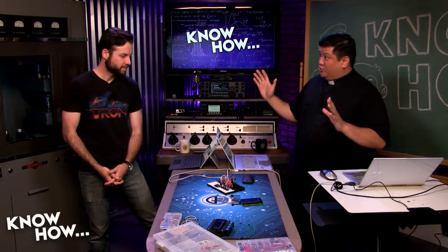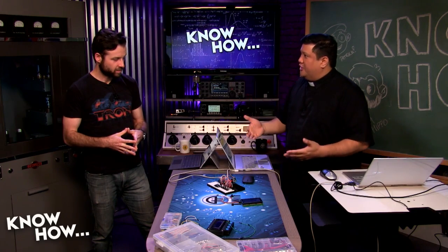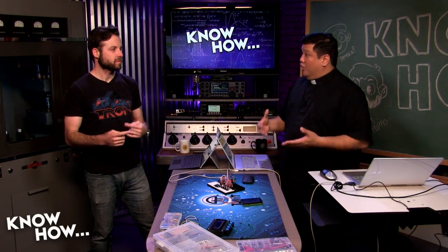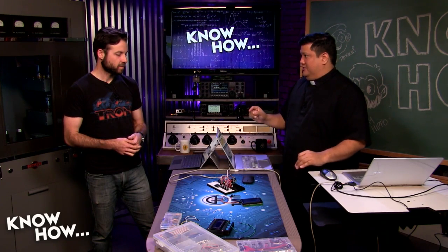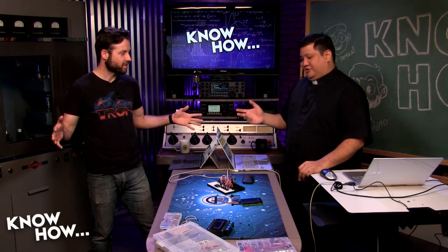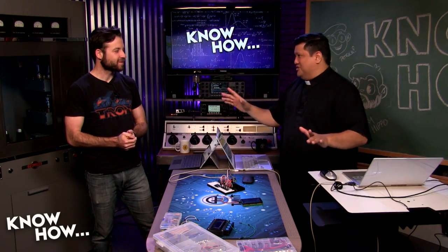So let's get ready for some screen-on-screen action. All right, so I2C, because it is a shared bus, should allow me to run multiple screens as long as they're not using the same address, and your wires aren't too long, and we have enough power. Yeah. And I've tested this before, so all those things are good.